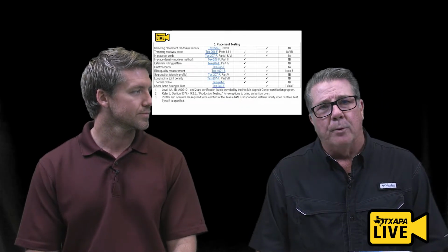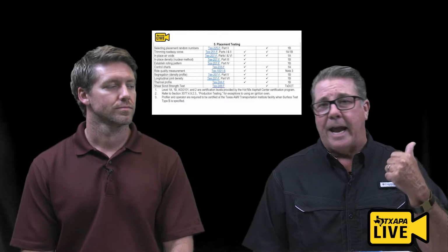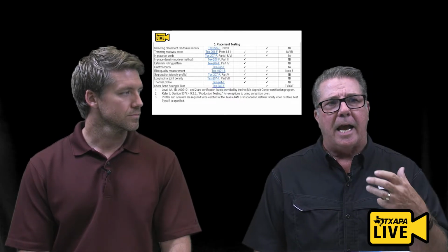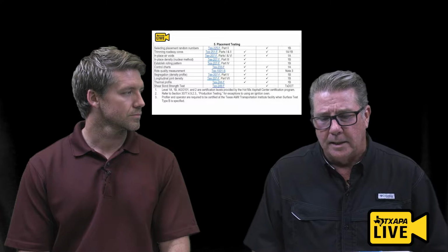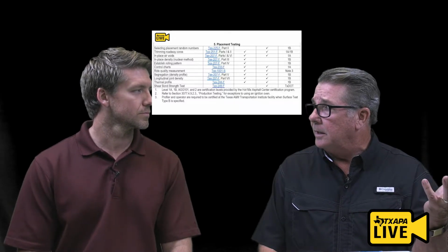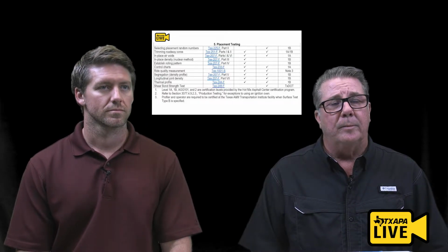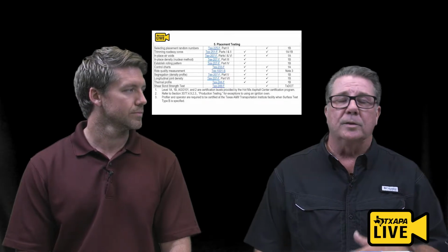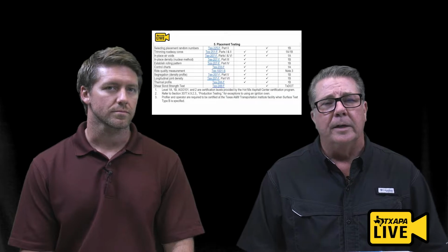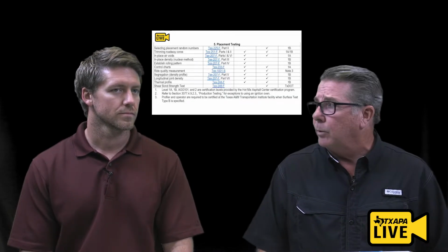Right. And I think that's real important for everybody to realize is that we do have these performance tests. We got the Hamburg, we got the overlay test, you got the shear test, and of course we have density. You have some of these performance tests that are going to help us prove the fact that we're getting durable, long-lasting material out there. And I think that, again, for informational purposes, the contracting community should know those numbers. Yeah. So as soon as those numbers become generated, get with your district, get with your area, and try to get those numbers back so that we understand and we know where we're at.